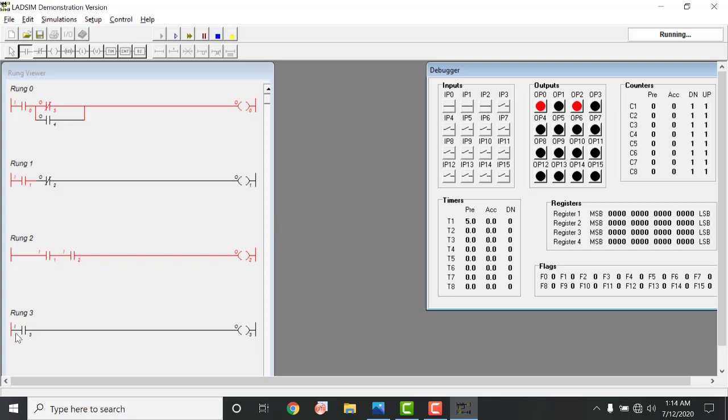Now we are using rung 3. When we use rung 3, remember that it would stop the complete process for 5 seconds because we have provided a timer of 5 seconds, and exactly after 5 seconds it would send information to this switch. If the switch becomes closed, our process will start again.